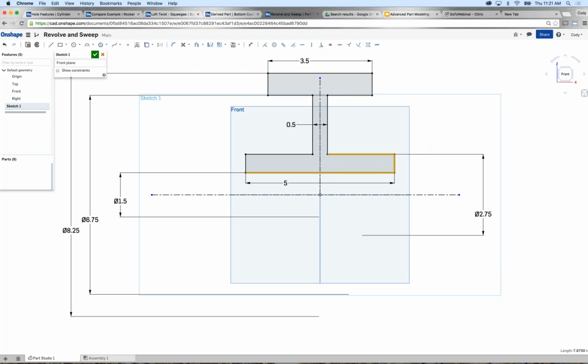And if you've come from a traditional CAD system, there is a difference between right to left and left to right. So if you are familiar with it, left to right will only highlight the things that are fully encompassed within your window, whereas a right to left will highlight anything touching your window. But absolutely, you can window select and select hundreds of things at once if that's what you're trying to do.